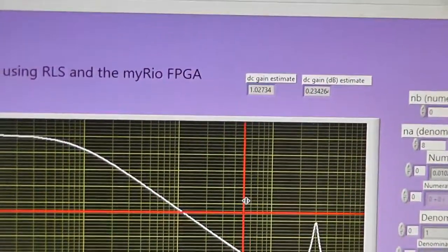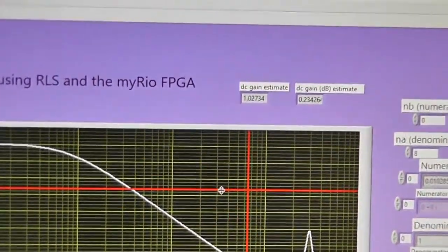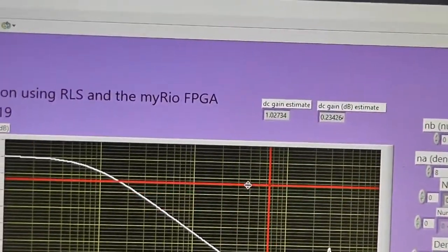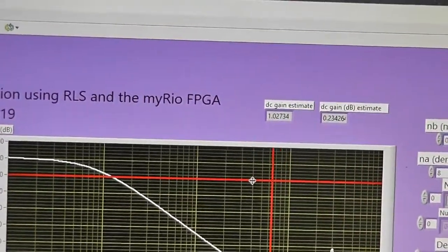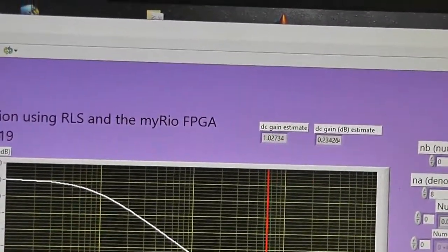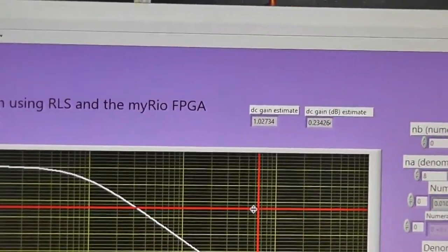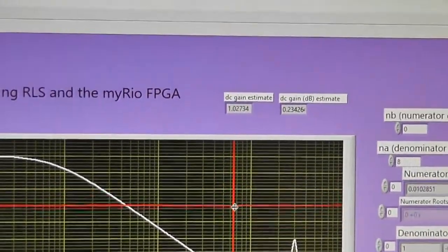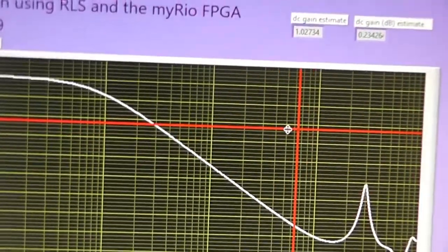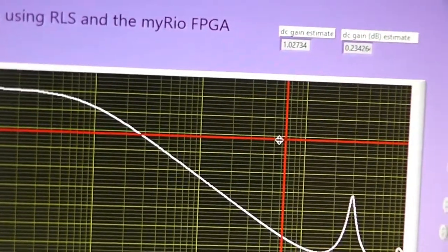That should be about minus 20 dB per decade, something like that. We can measure anywhere. We can take, what do we take? About there, that's 5 dB to 25 dB or something in a decade. Or we can take it in an octave, which might be easier, because it's not right on the grids there. It's a bit harder to find.